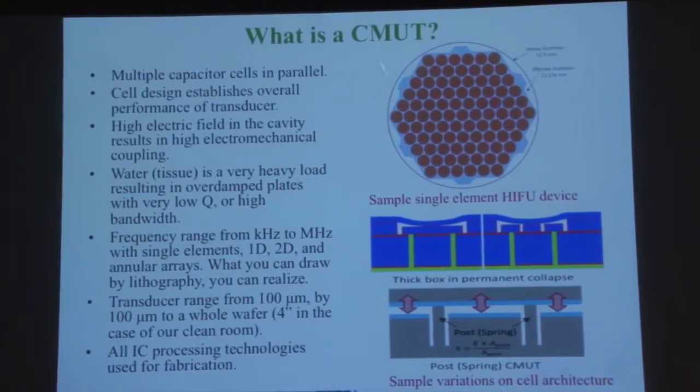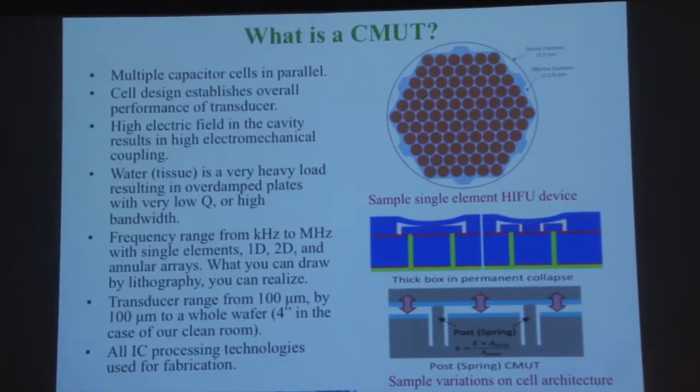And then it's micro-machined, so this is built in an integrated circuit fabrication facility, and that presents all the advantages of IC manufacturing in terms of control, reliability, scaling in small or large size and dimensions, both horizontal and vertical. And it's ultrasound, so we can go in frequency all the way from maybe 10 kilohertz to 100 megahertz, and they're transducers, they're reversible, they can transmit and receive ultrasound as one would like to see.